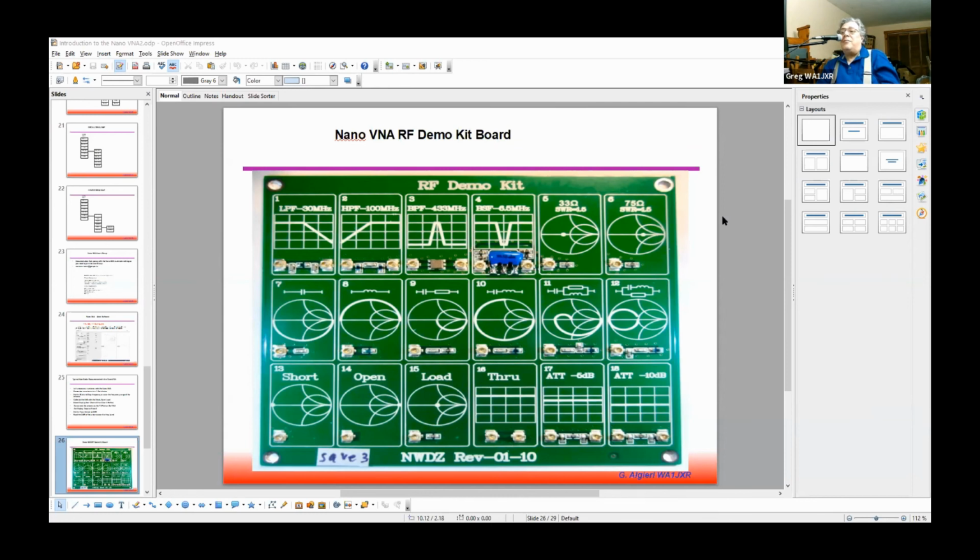If you've calibrated and it hasn't been an extremely long time, and the calibration frequency range that you have will work for the thing that you're trying to measure now, then there's no reason why you couldn't use it. So there's two things that happen. You want to optimize your calibration for the thing that you're trying to measure, so you get the most resolution within your measurement. So that might be a reason why you might want to recalibrate for some particular device.